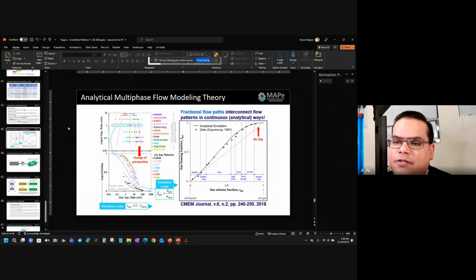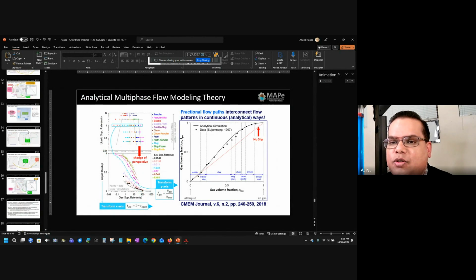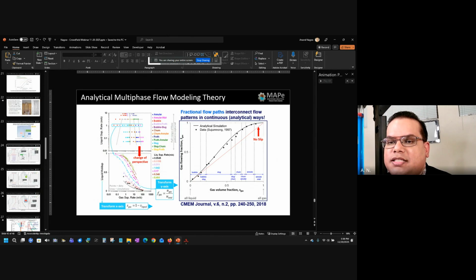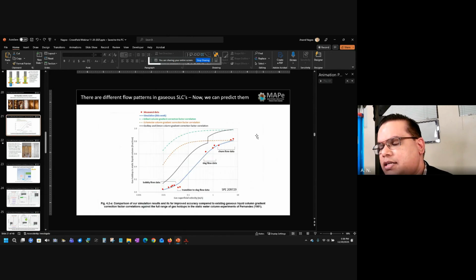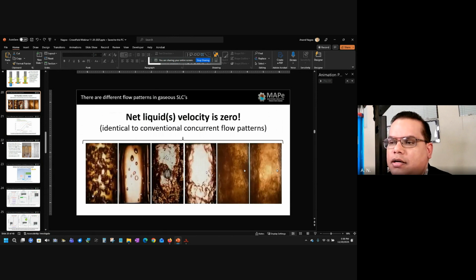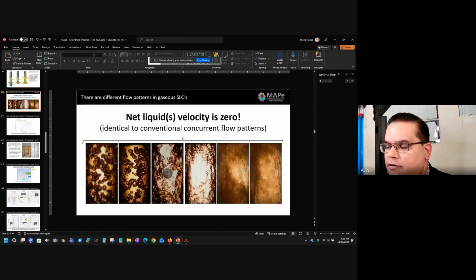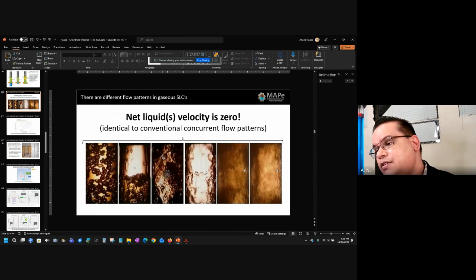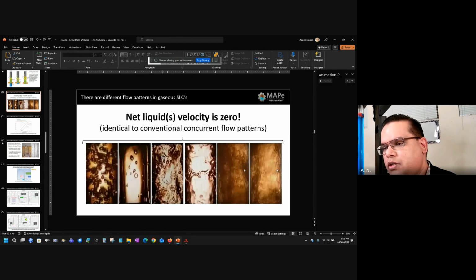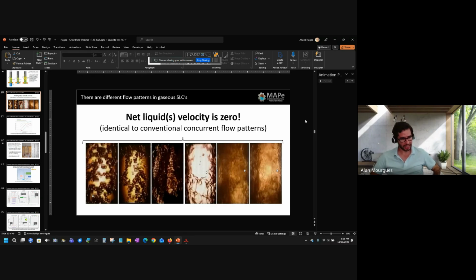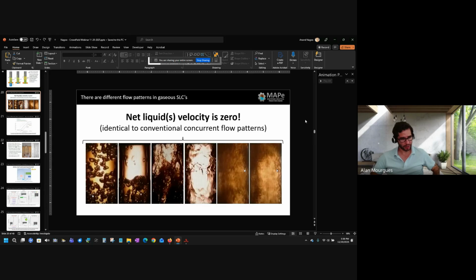So now you're accounting for the flow patterns in these fluid levels, and including their local behaviors as well as their macroscopic behaviors, and that allows us to get a much more accurate understanding of the gas evolution profiles, all these different profiles, right? In the fluid columns, not just in the fluid columns, but when you have concurrent flow, and when you have countercurrent flow, which we haven't talked about as yet, but that's in the whole world of liquid loading.